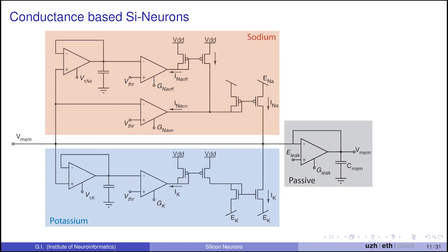And that's basically the same as the potassium channels in real neurons and in this simplified RC circuit I showed you. And so then we start to discharge Vmem, and then at some point Vmem will go below V threshold. It stops, it switches this off. At some point, the delayed version of Vmem goes below V threshold, it switches this off. And this lower delayed version of Vmem goes below this threshold and it switches this off. And so then we go back to this passive case where Vmem is being pushed passively with an RC behavior